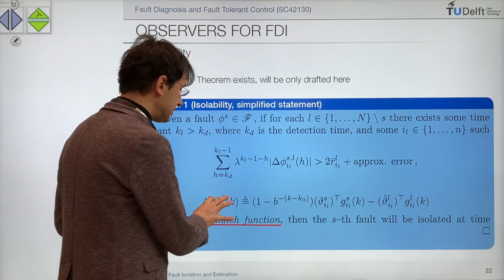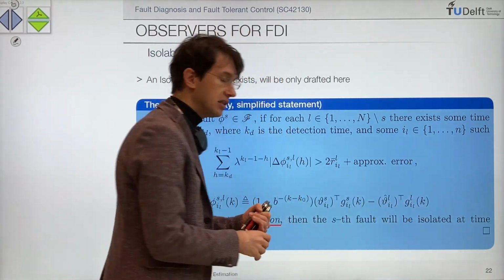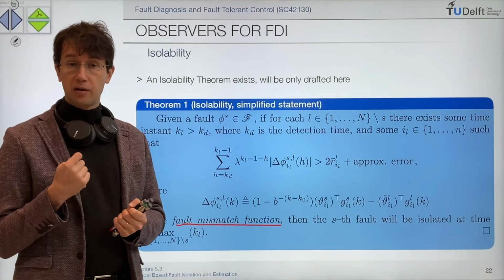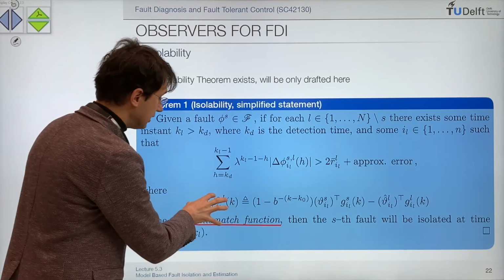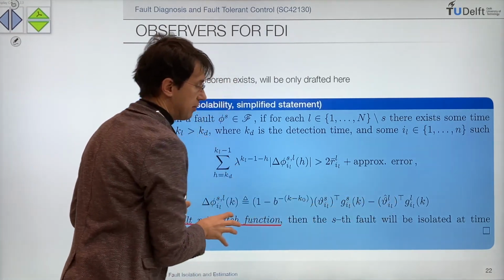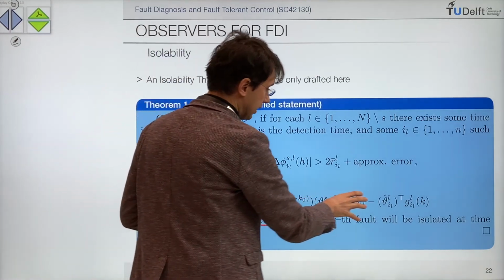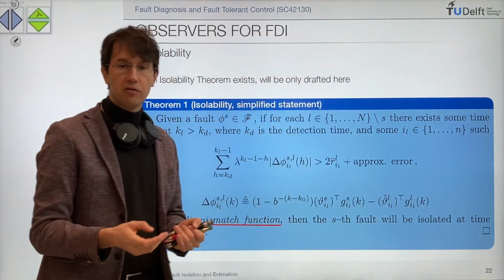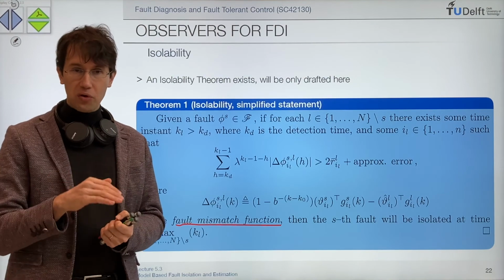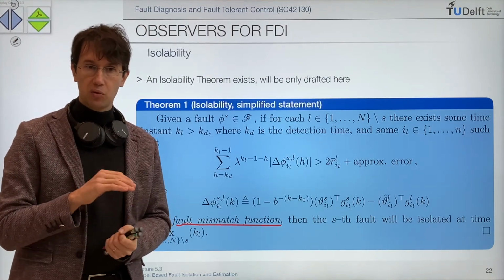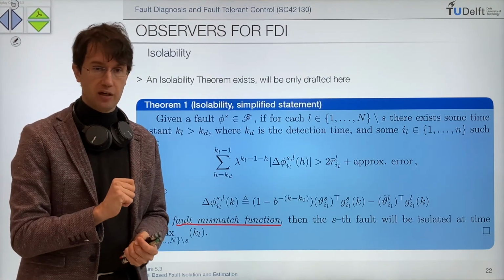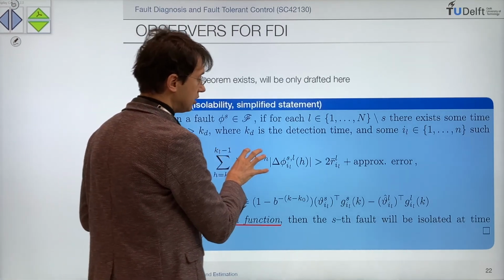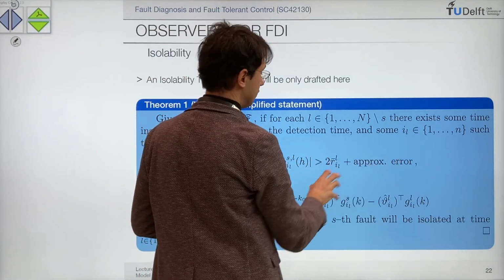So basically, this difference, if you write the residual dynamics for a case of a non-matched fault, you are getting this term in the residual dynamics. So this is the term making the residual big when a fault is not matched. And you want the residual big in that case because you want for that hypothesis to be falsified. So this is the condition that guarantees that hypothesis is falsified.